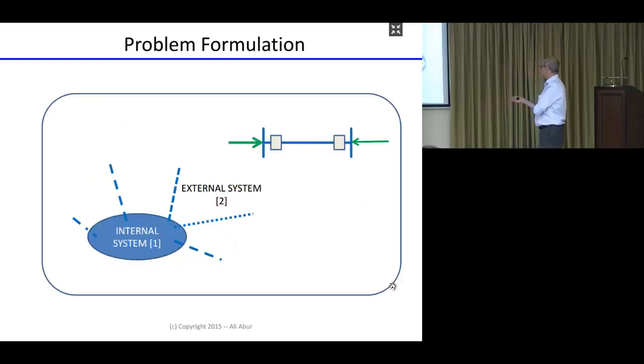So this equivalence can help us in identifying an external line branch outage, because if you think about it, essentially a line outage will be equivalent to a change of a pair of injections at the terminals of this outaged branch. So the branch remains closed, but you notice this jump in the injections at the terminals. So the problem turns into identifying these jumps in the injections rather than a change in the topology.